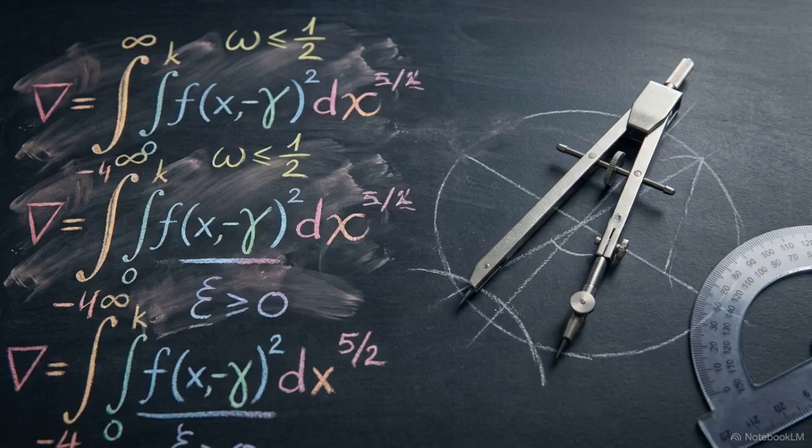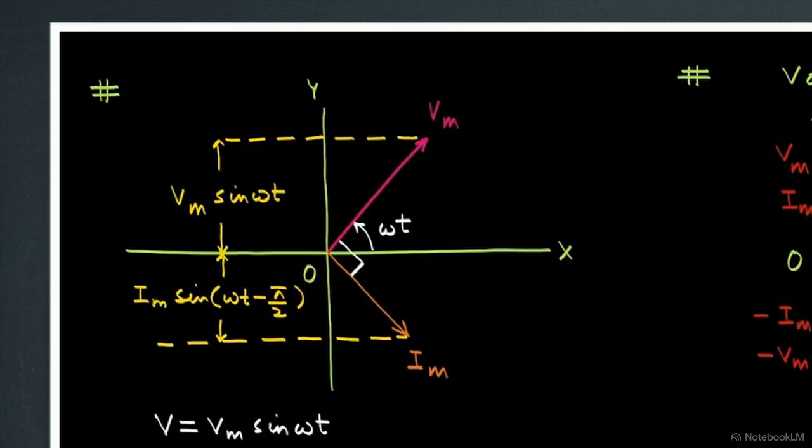Translating phase shifts in your head is difficult. Engineers use a geometric tool called a phasor diagram to visualize out-of-phase waves without doing complex calculus. This sets up a static XY coordinate system where voltage and current amplitudes are straight vector arrows. Geometrically, the current vector is locked precisely at a right angle behind the voltage vector.